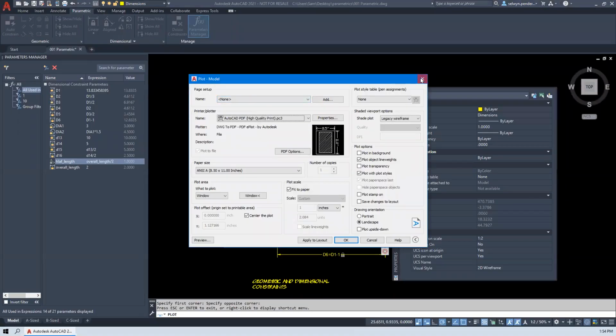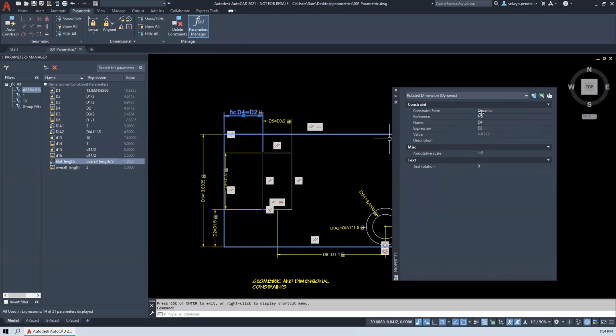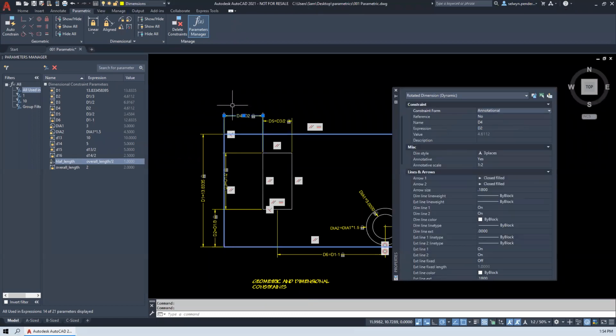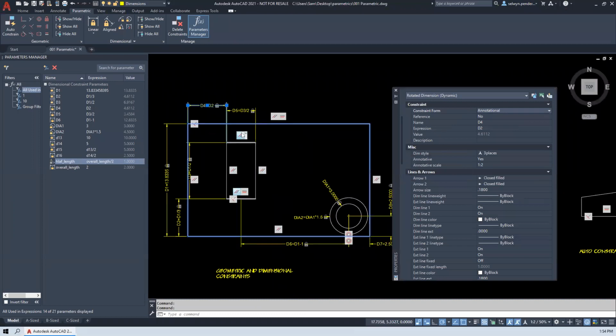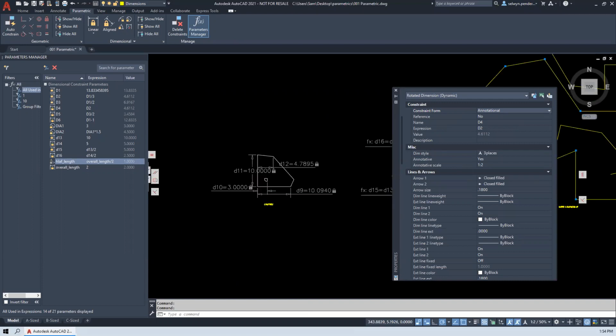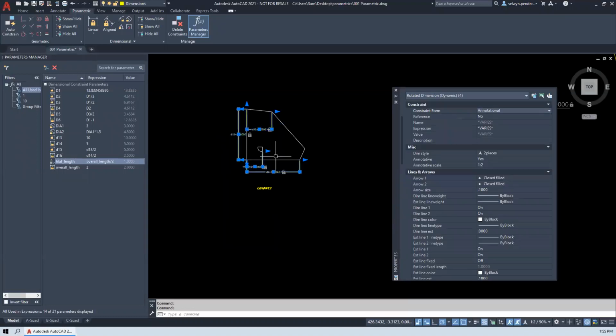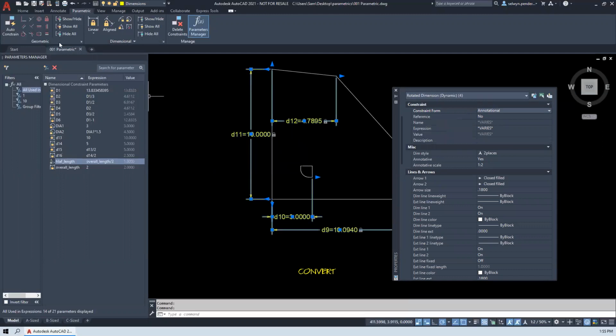So if you're going to print the parameters that you have in your drawing, you need to change them to annotational dimensions. So you can come through and select all like-minded dimensions. So over in this one here, if I grab these ones here, select, change it to annotational, they will now print. However, you'll recall that we're showing D, whatever it may be.